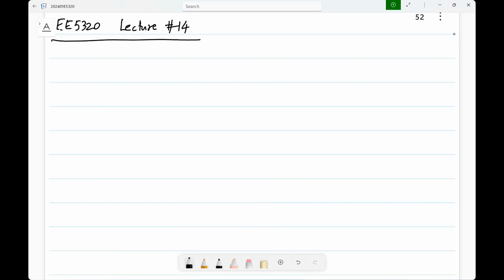And then there is random noise, which again is inevitable, at least the thermal noise part, right? Or that white noise in any component that you cannot get rid of. So you can calculate them. Again, you can try to keep the noise level below the required limits, etc. And then in addition to white noise, there is flicker noise, which is not as fundamental, but will anyway be there. So again, you need to know how to calculate those things. So these are all things that affect you.